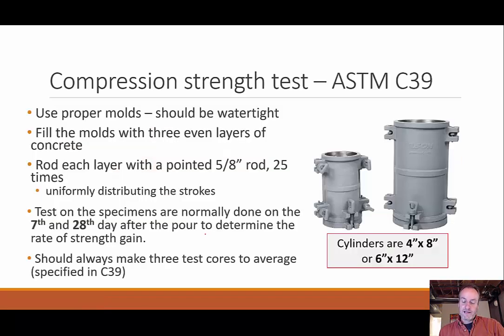And we've done this before. We've talked about the compression test with our molds. You should have put it in your cylinder the same way we did it in our slump cone, where you're rodding it. You have 3 layers, and we're testing on the 28th day.